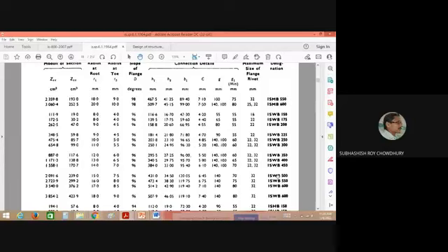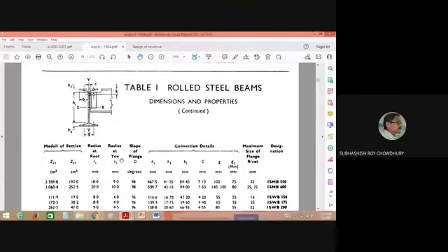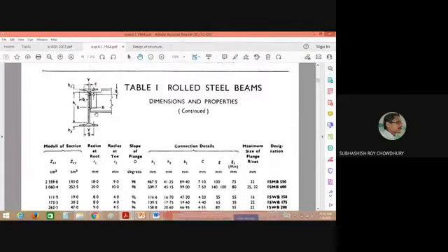So whenever you consider designing a beam or column or any structural component of a steel structure, when you choose the beam section, like these I sections, you consider the M section, that is the medium beam section. So ISMB section you may consider for the purpose of designing. So these are the details for the I sections that are generally used for designing of steel structures.